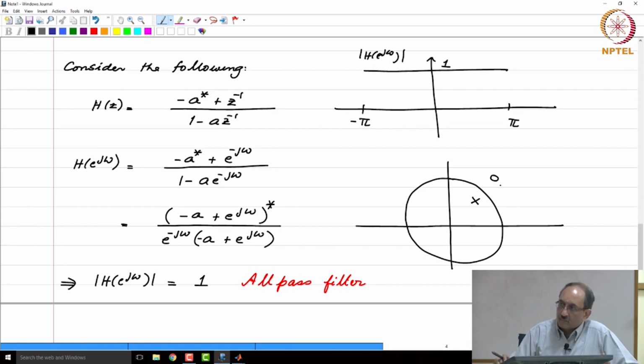Yes. So, reflection around the unit circle. Yeah, the distances won't be maintained. So, this is different from the reflection that you are used to, saying reflecting something about the y axis. There the distances will be maintained, right. Whereas here what we mean by reflection is, if you had r e to the j theta, the reflected root about the unit circle is 1 over r e to the j theta. So, here we are not meaning the distances have to be maintained.